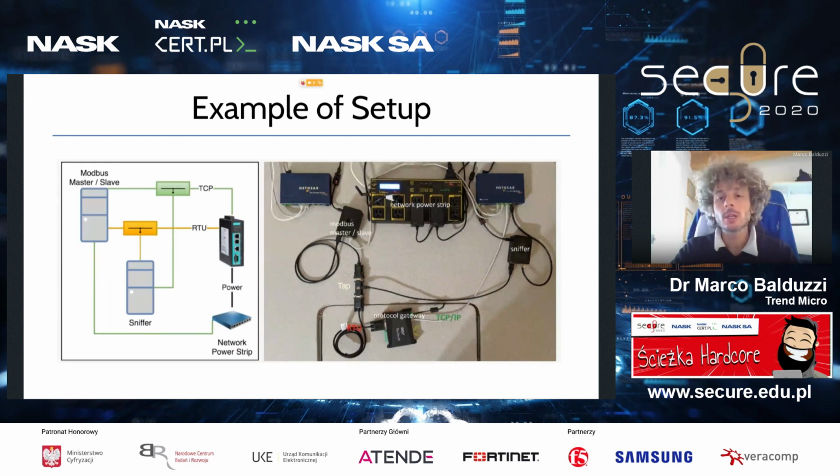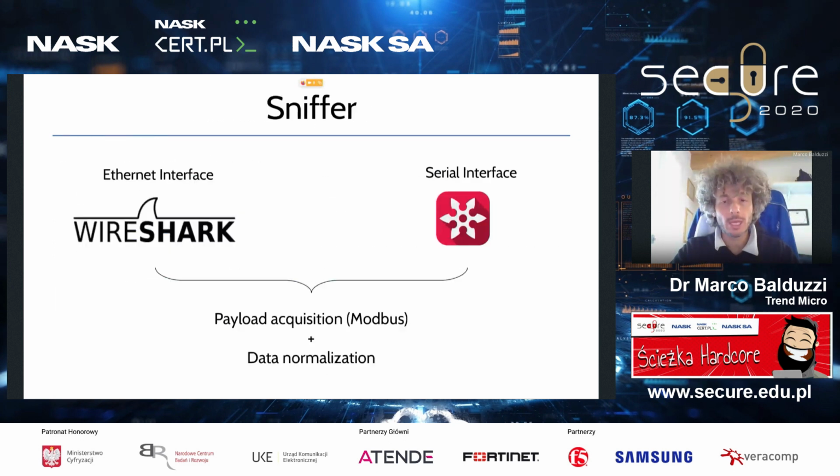On top of that, we had Wireshark for monitoring Modbus TCP, and IO Ninja, which is a fantastic tool. We use it for monitoring the serial interface, so Modbus RTU.